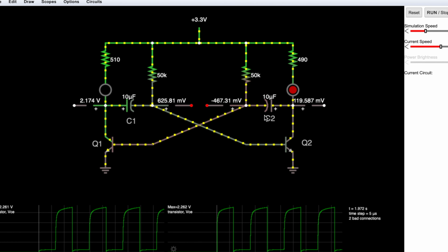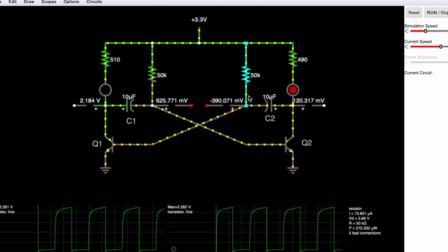And this is why you will also realize that this resistor, which is R3, and C2 are important for the switching times, because the amount of time taken for C2 to be charged to 0.65 volts or 0.62 volts, whatever is the switching value for Q1 for the base emitter voltage, will decide the time taken by the circuit to switch on and switch off. So right now the right LED is on, the left LED is off, and in a few seconds, and mind you, the simulation is really slow. As you can see, each time slice is only 200 milliseconds or so. So right now the simulation is actually happening at a very slow speed.